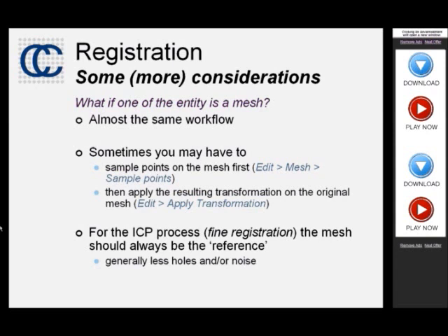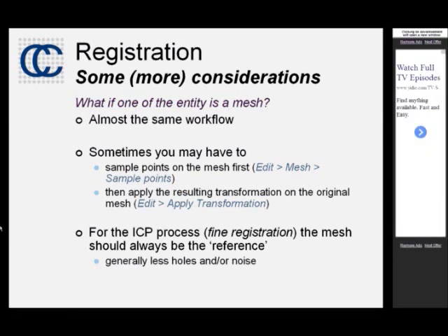So that's it. Yeah. I have a quick question. If you have 2 point clouds which share some common features, let's say it's a roadway or could be part of a house or a building, whatever, but then there's a significant portion which is different, it's also possible to segment the part that is different. So basically cut it out and then register the 2 parts that are similar and then apply the transformation to the part that's been segmented. Oh, yes. It's a very good remark. Exactly. You can do that as well. This is a bit of a trick, but this is perfectly right.